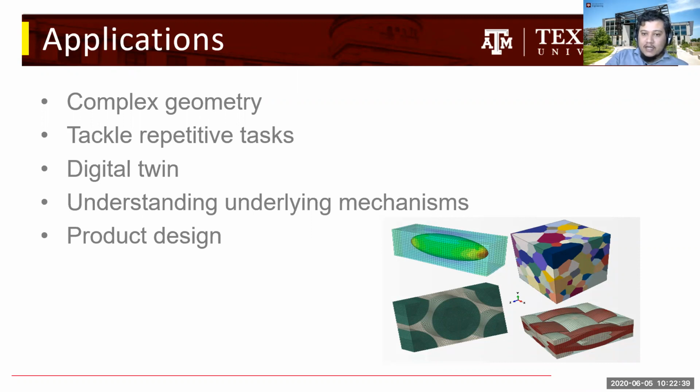conditions as well. For example, if we are doing a tensile test on a dog bone specimen, we know that necking occurs in the center, and we have far field results like the value of the displacement and the forces. We can measure that. But what is actually happening within that necking region is some kind of void growth, or we call it ductile failure. So we know that this is happening, but how the void is behaving in a certain environment, in a certain material, we can definitely investigate experimentally, but it's going to take a lot of effort and complex experimental setups.